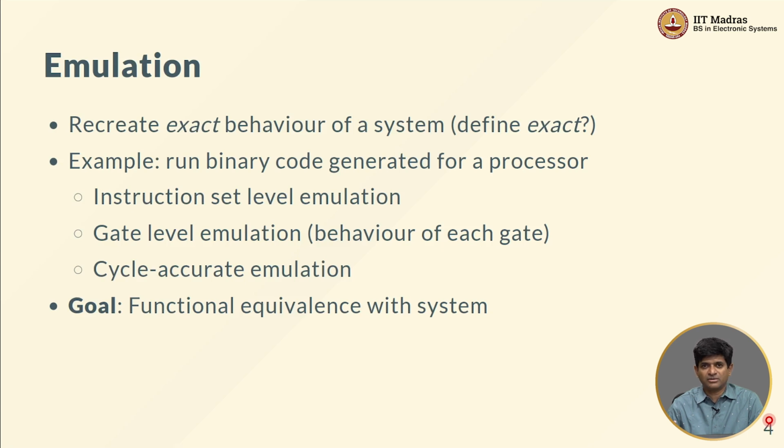So, emulation, once again, the goal is that it should be an accurate model of the system behavior, but once again accurate at what level, right? Primarily what we want is that the instructions that are executed by the CPU should be accurately modeled within the system. We sometimes call for something called cycle accurate emulation, and this usually comes in when we are talking about co-simulating.